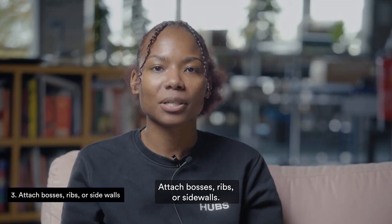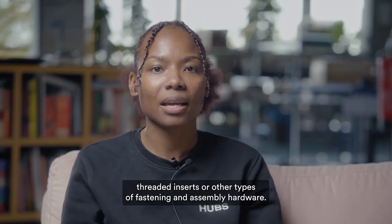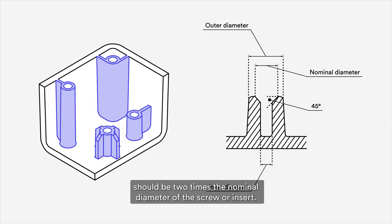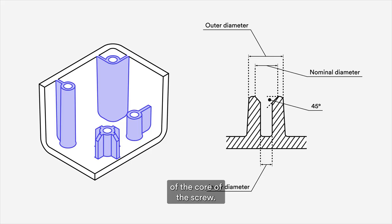Attach bosses, ribs, or side walls. Bosses are cylindrical projections with holes designed for screws, threaded inserts, or other types of fastening and assembly hardware. When bosses are used for fastening, the outer diameter of the boss should be 2 times the nominal diameter of the screw or insert. Its inner diameter should be equal to the diameter of the core of the screw.